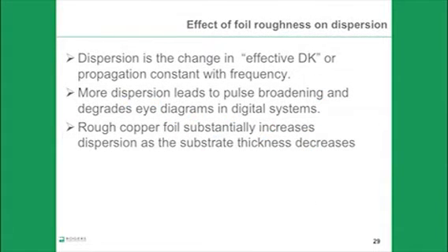So remember, dispersion is a change in effective dielectric constant or propagation constant with frequency. More dispersion leads to pulse broadening and degrades eye diagrams in digital systems. And rough copper foil substantially increases dispersion as the substrate thickness decreases.